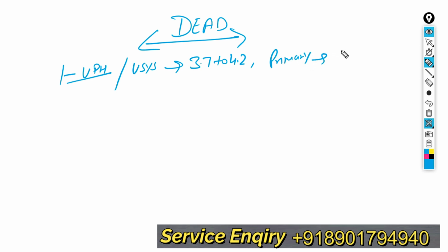If you do not get this voltage, there are two situations: no voltage but the line is okay, or a short circuit. If this line has a short circuit, there are many methods I have already described in many videos. You can watch those videos and find the short circuit. Now, if there is no short circuit but still no VPH, remember VPH is the primary voltage. Without VPH, your phone does not turn on. So the first job is to make the VPH.